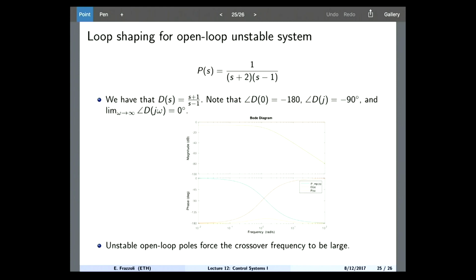No. You need a fast computer actually stabilizing those systems, because if the airplane just flips and goes unstable in a fraction of a second, you want your computer to be able to counteract that faster, okay? So non-minimum phase zeros limit how quickly you can move. Open loop unstable poles force you to move fast, okay? If you have both, you're in trouble, okay?